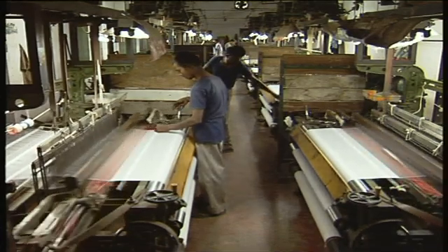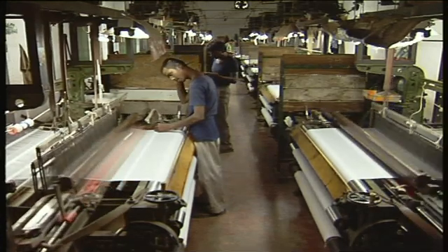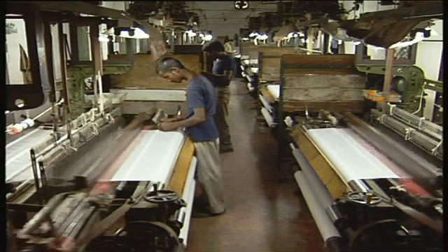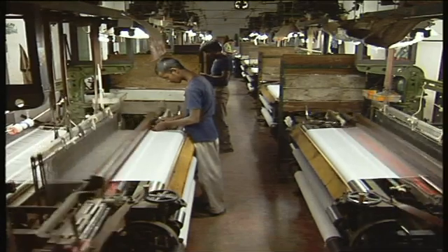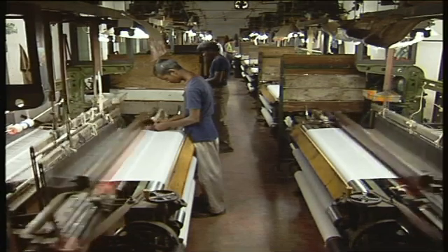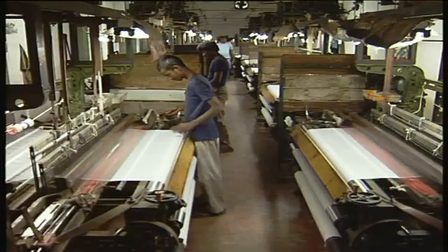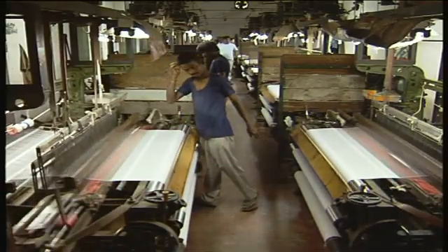When the belt is on the loose pulley D, the pulley will rotate, but the crankshaft will not rotate. Therefore, the machine can be stopped. By moving the belt to the fast pulley C, the loom can be started or stopped at any time.